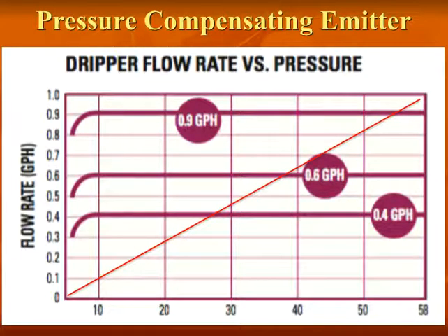Pressure compensating emitter. Netafim makes 3 emitter discharge rates in their BioLine that are pressure compensating: the 0.42 gallon an hour, 0.61 gallon an hour, and a 0.92 gallon an hour. They measure gallons per hour because it's such a slow flow rate. Gallons per minute per emitter would be such a small number, it doesn't make much sense. We'll be using exclusively, and this is one of the variables that we reduce, the 0.42 gallon an hour emitter. This emitter will work in all soil types from clay to sand and everything in between.